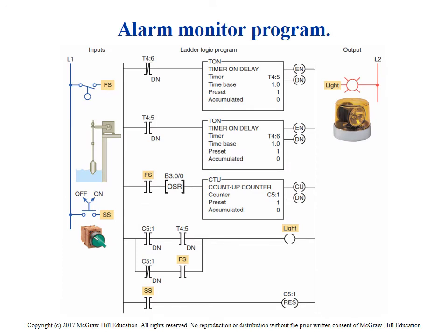Okay, so here we're looking at another application where they're using timers, and it looks like a flasher circuit to me, 4, 5, 4, 6. Remember, this is normally closed and normally open. That lets me know right away it's a flasher circuit. So that flasher circuit is going to come over here, trigger this, and cause this counter to constantly count. Every time we hit the selector switch, it's going to reset.